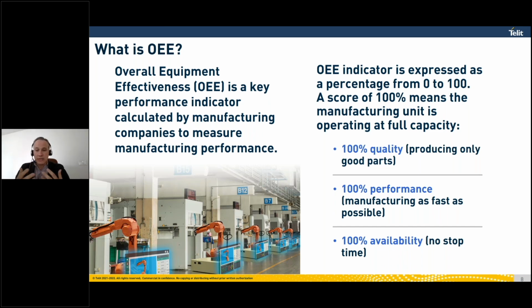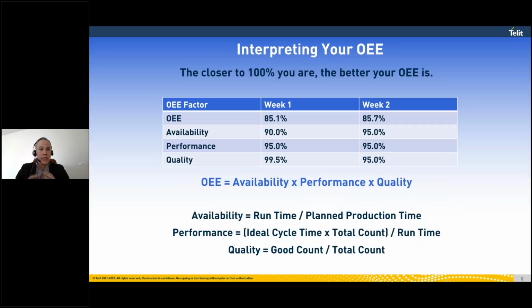So when your line is down, eventually it is down because of different reasons. Maybe it's down because I am setting up the line for a new part number to be produced. So that was a planned stop. Or maybe it's down because my machine is broken and now I need to stop this process until this is fixed. And this is certainly impacting my productivity there. By factoring these three different pillars for your OEE, you can calculate how close you are in terms of the effectiveness that is expected for your process.